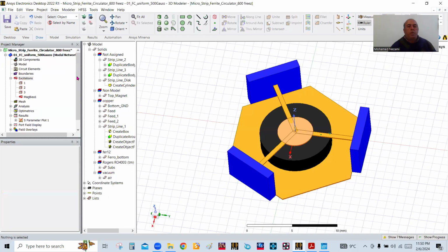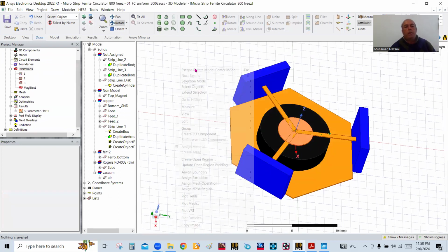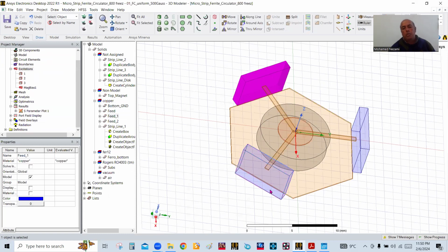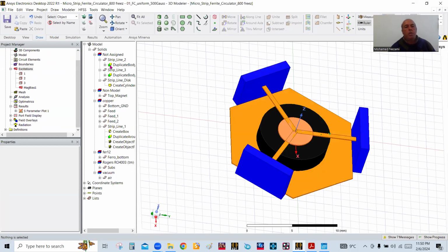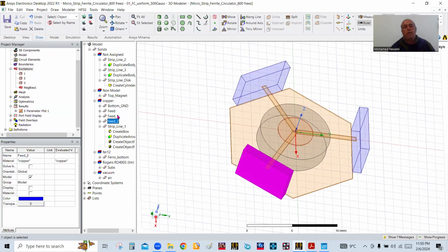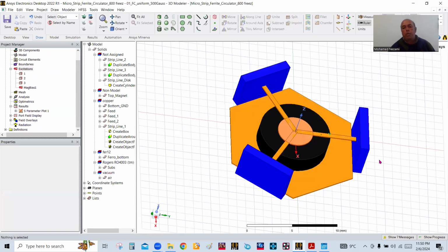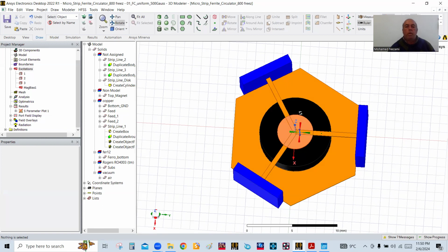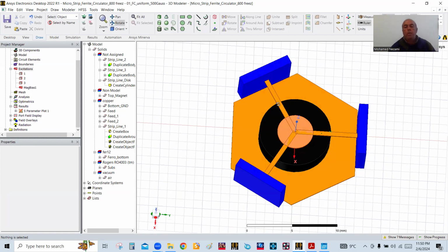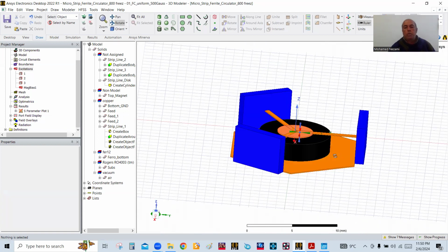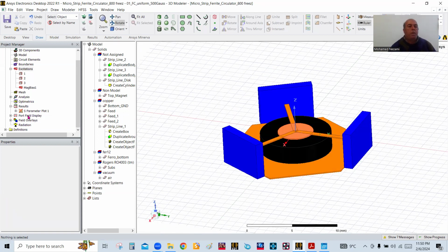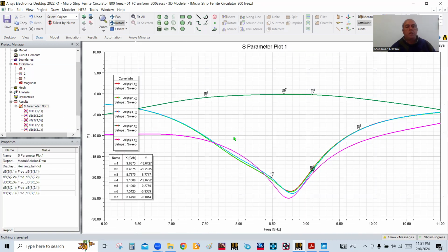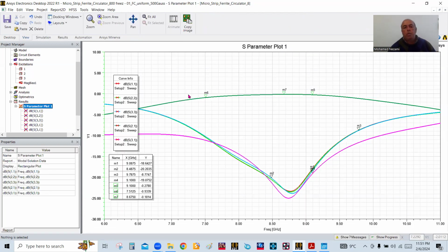All right, so once you do that, of course, you have to create electrical excitation to this. And the way this is done is I attach these ports, okay? And these are metal blocks, basically. Right now they're copper, but you can make them aluminum if you want, because eventually this goes to a circuit connection somewhere. And when you run this, that's what I get right here with these parameters.